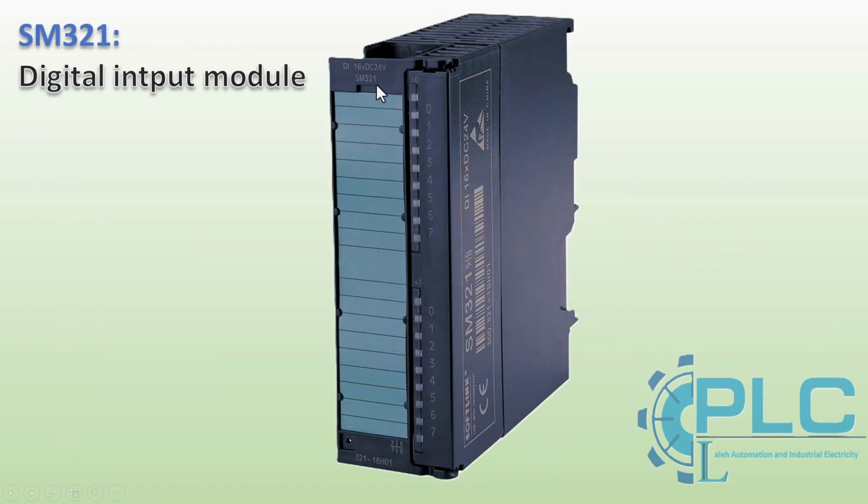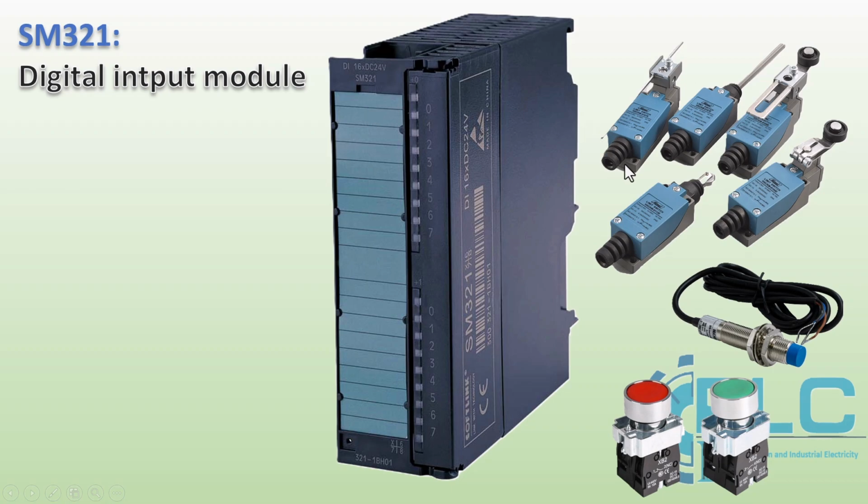The SM321 is a digital input module in the S7-300 PLC series. It receives signals from field devices, such as push buttons, limit switches, and sensors, and converts these signals into a format that the CPU can process. The number of inputs available in the SM321 module can be 8, 16, 32, or 64. The choice of module depends on the project's requirements and the number of digital input signals needed.